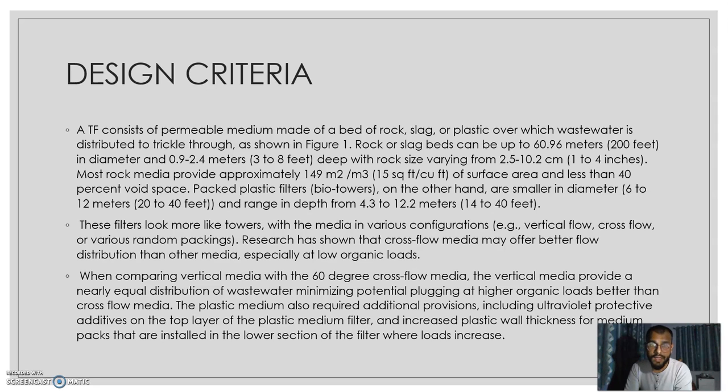Research has shown that cross flow media may offer better flow distribution than other media, especially at low organic loads. When comparing vertical media with the 60-degree cross-flow media, the vertical media provide a nearly equal distribution of wastewater, minimizing potential plugging at higher organic loads better than cross flow media.